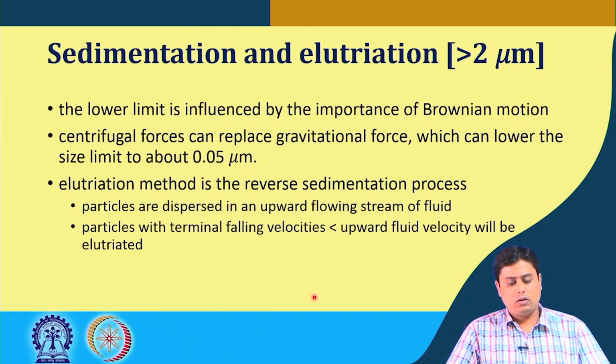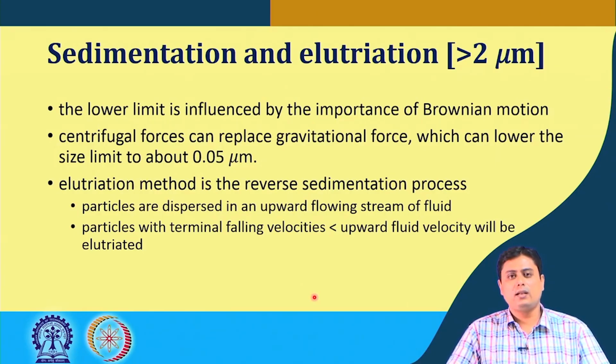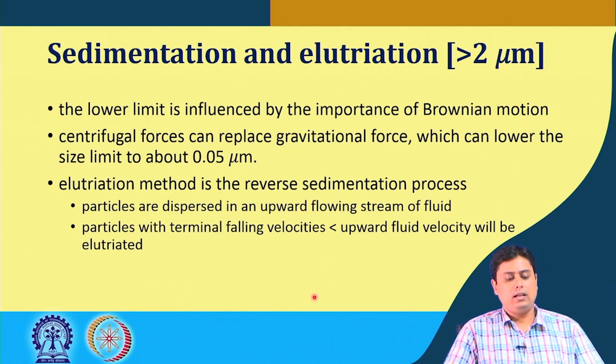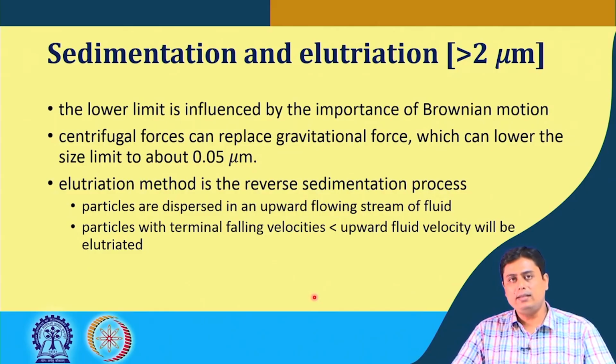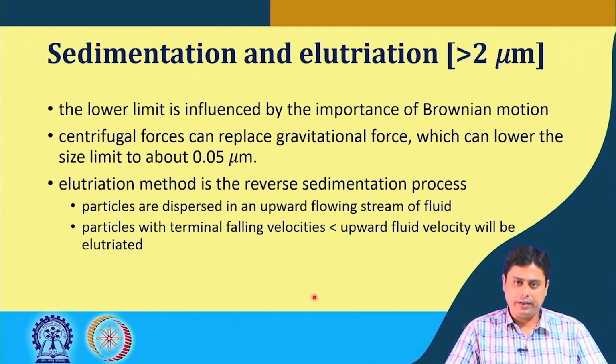Centrifugal force can replace this gravitational force. Instead of simple normal settling cases, we can introduce centrifugal forces in that domain to enhance the settling process, and in that case particles of about 0.05 micron size can be identified or settled.